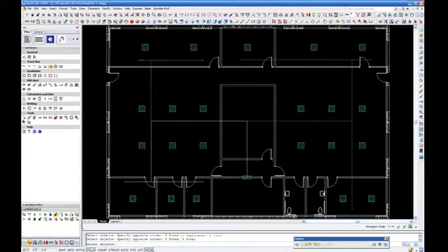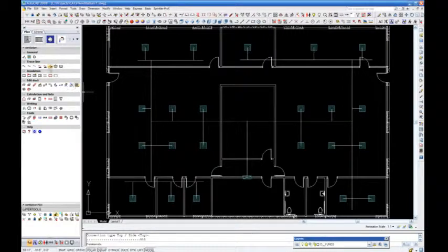In the AutoCAD command, we are asked whether to connect the diffuser on the top or the side. We will select the top. And now all connections between the duct center line and the diffuser are completed. In the AutoCAD command, we are prompted to select the lines to be deleted. In the CATS Commander, we select Automatic Duct Generation.